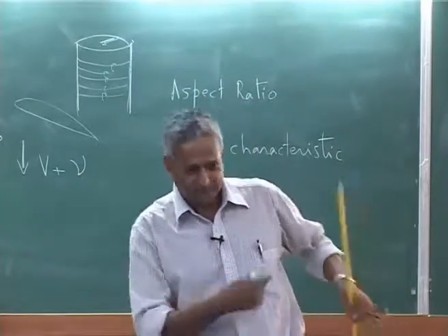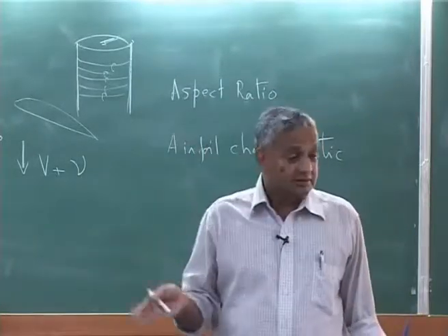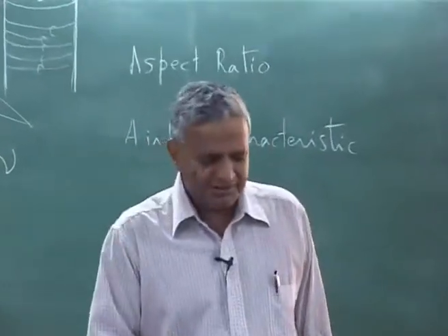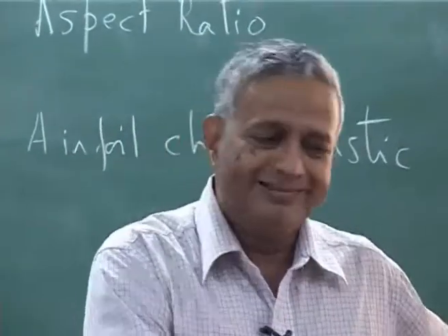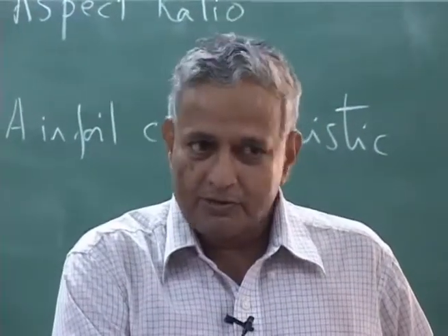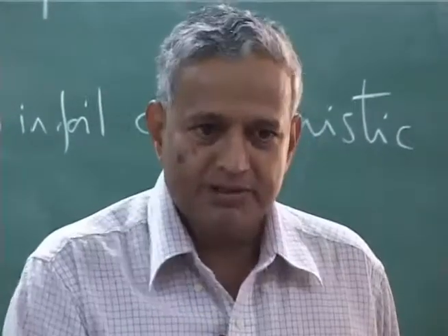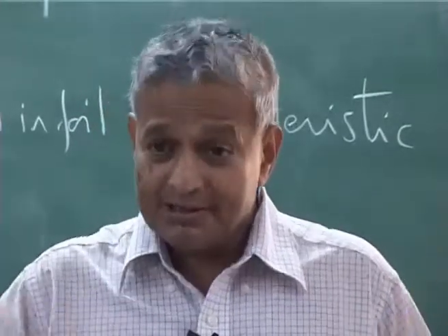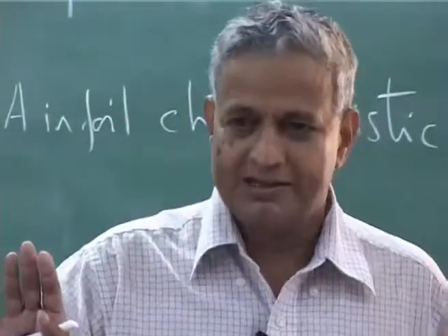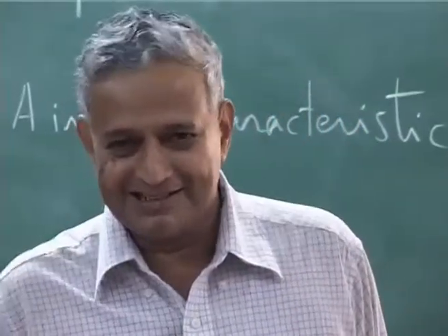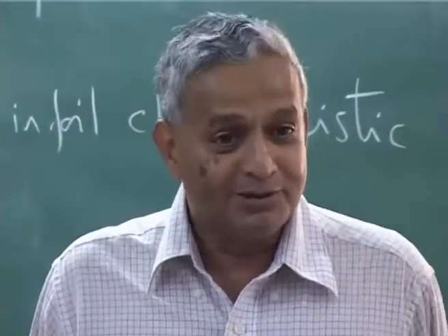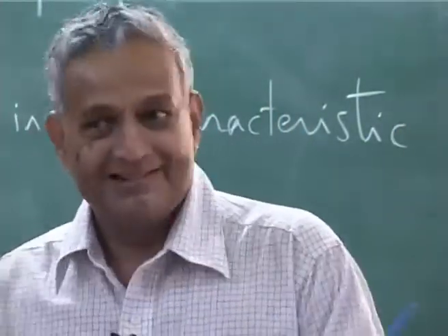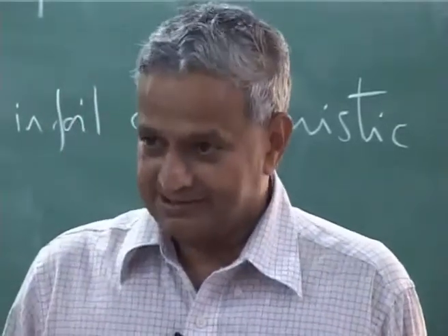I will show you later how we use it, because if you want to have vortex theory, then you need to sit and develop. This is computationally more intensive, whereas you will find even with momentum theory, the results which you predict are reasonably good, pretty good I would say, but you have to make some corrections here and there. With that your results will be good, and that is why momentum theory is still used in rotor analysis.